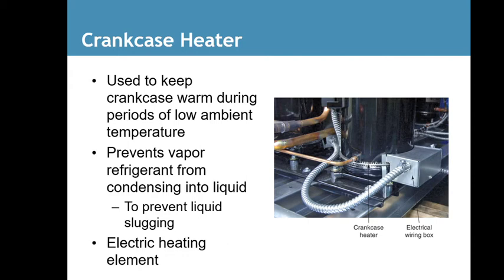Nowadays, they use power. This is something that is expensive to put in if you need to have a thermostat to turn it on only in cold weather or cool weather even. But the real problem is you have to think about this heat element going around the bottom of this compressor. And it's hard to see it in this picture, but it's that little silver ring around the bottom where the arrow's pointing. On big units, yeah, you use them and they're worth the power.